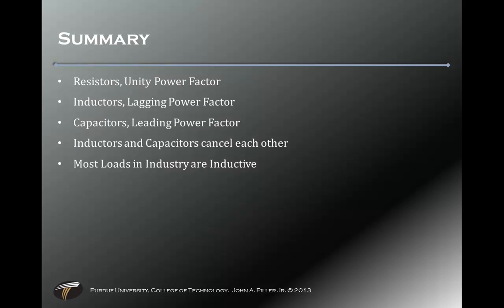Resistors have a perfect power factor, unity. Inductors have a lagging power factor. Capacitors have a leading power factor. Lagging power factor means that the power triangle has a positive angle. Leading power factor means the power triangle has a negative angle. Inductors and capacitors are 180 degrees out of phase from each other.